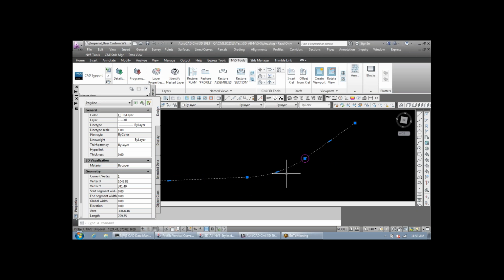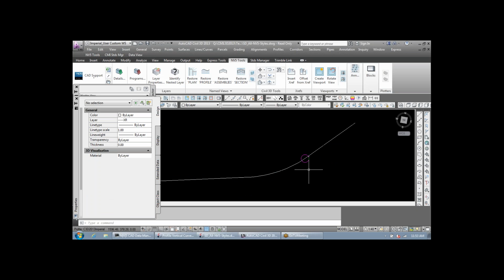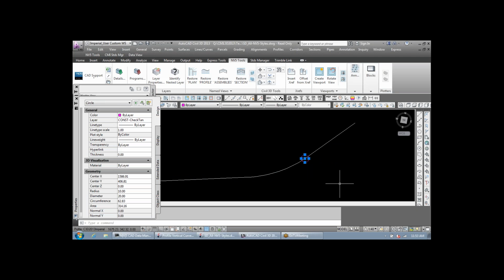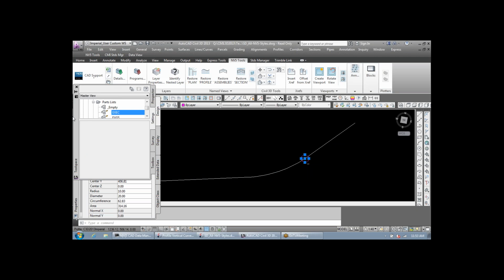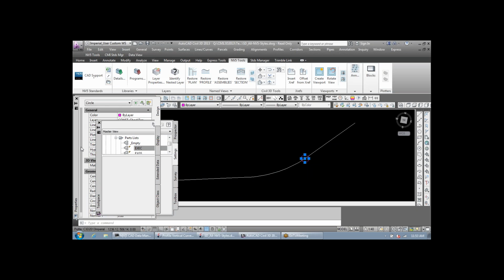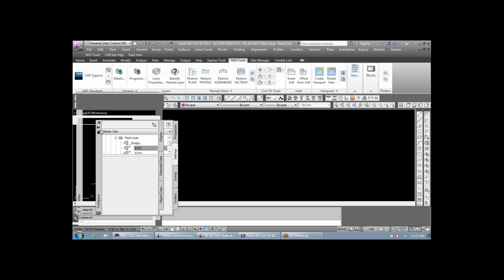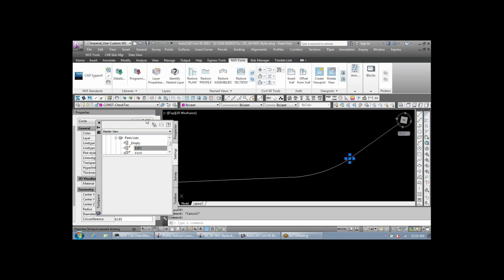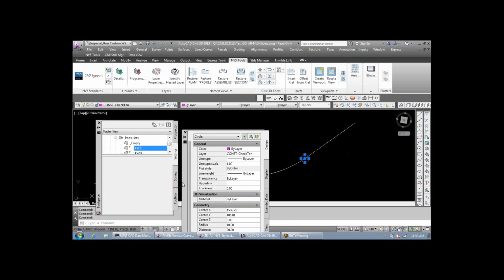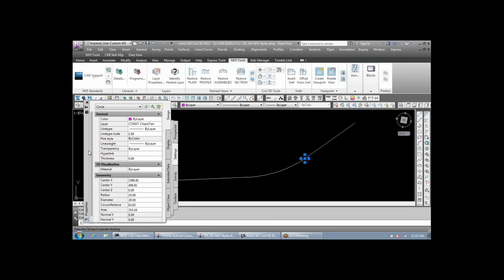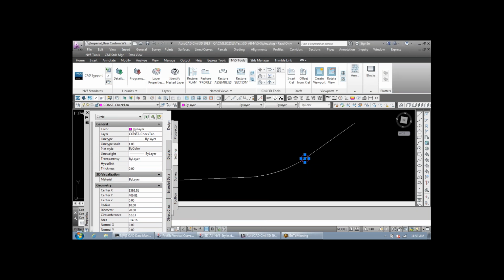So then you can come back and fix your tangency. You will have to delete that. It is just a simple circle, just a regular AutoCAD circle. So you will need to delete those after you're done fixing them. It is on its own layer though, construction check tan layer, so you can layer isolate or you select similar without destroying. Is that a no plot layer? It is a no plot layer. All construct layers are non-plottable layers.